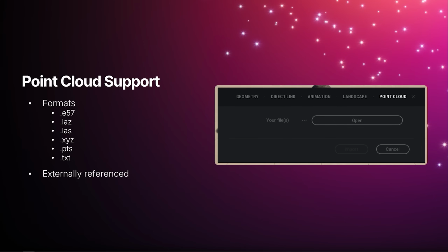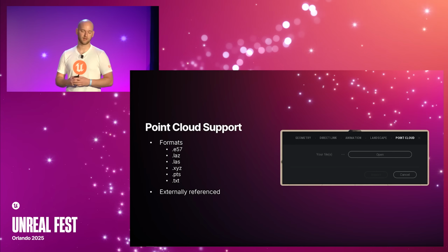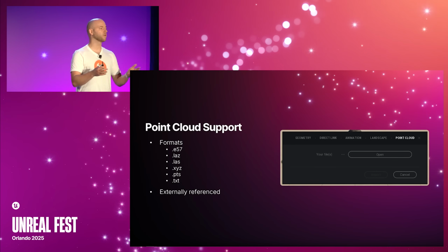Point cloud support, we support most of the major file formats, E57, LAZ, LAS, a few others. Fun fact, these are actually externally referenced files. So we do the hard work of streaming the data in as we fly around the scene, and that way you don't have to always crash Twinmotion with crazy data sets. And sometimes it affects points will pop in and out, or things that are behind you will stop casting shadows, but it's still really cool and easy to use.